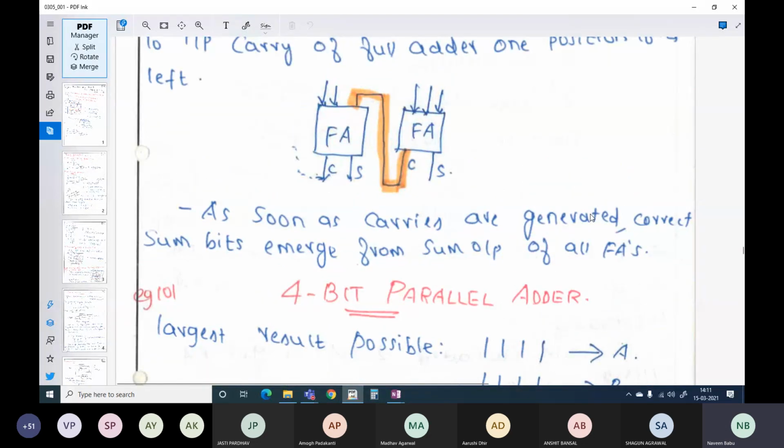In the parallel addition, what you saw in the last class was that your carry here will propagate every time. Which means that the output across this sum, across this full adder block, you will get only after you get this carry here. Okay, so that is the disadvantage here. But with this particular disadvantage, it is manageable when compared to a serial bit addition.